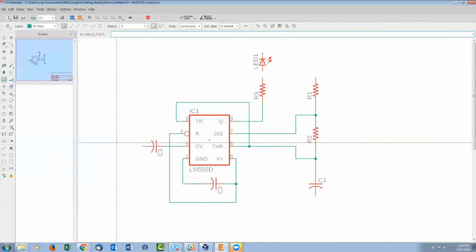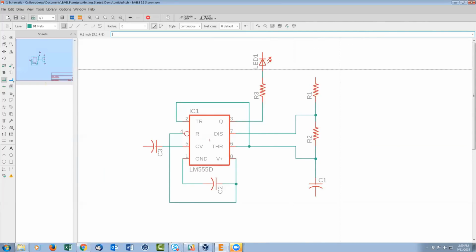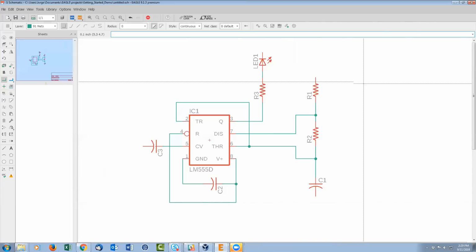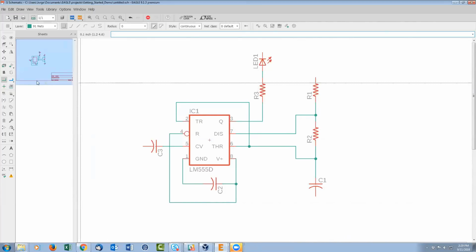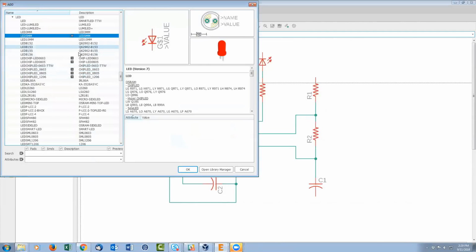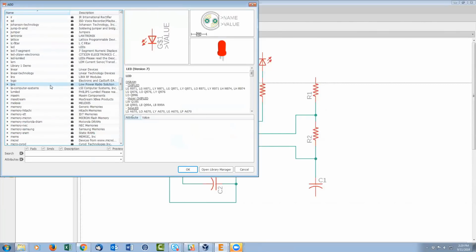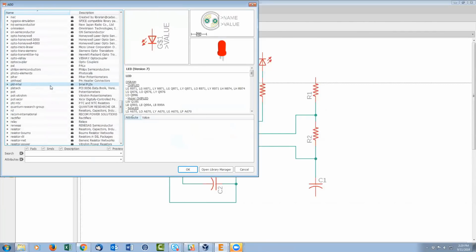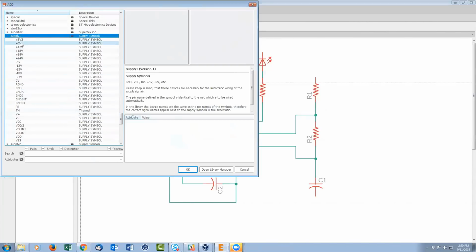And now, so far, what we are missing are the rails, right? We don't have any voltage source in here. We don't have a battery or plus 5 volts or anything like that. So let's go ahead and add those in. We do that using the supply libraries. Eagle ships with 2. Supply 1 and supply 2. And these contain the supply symbols.